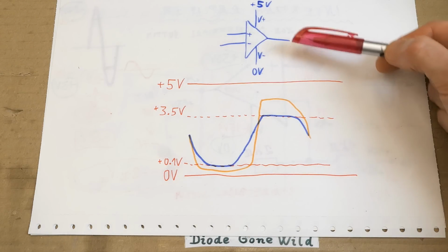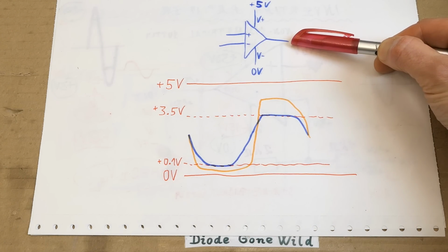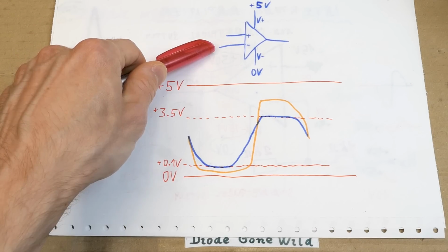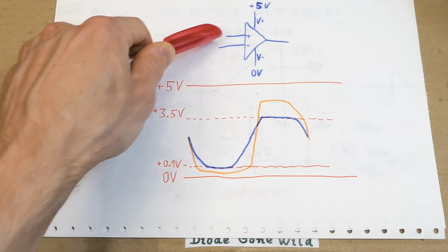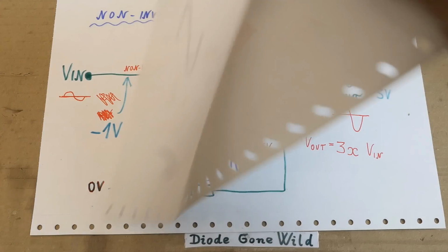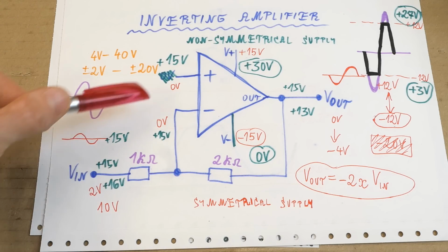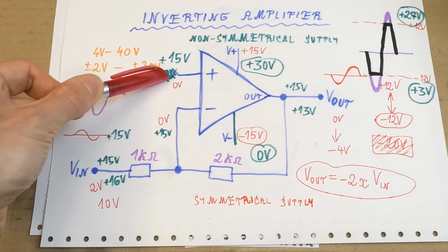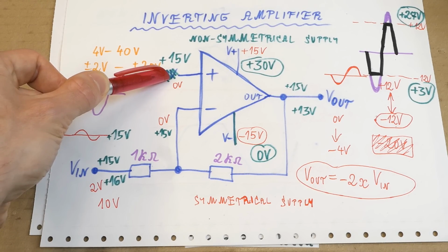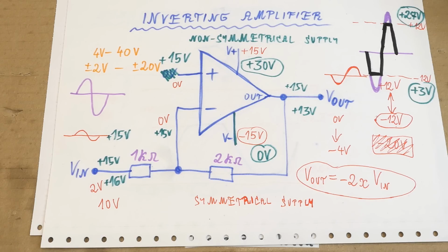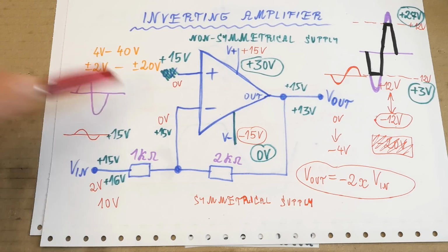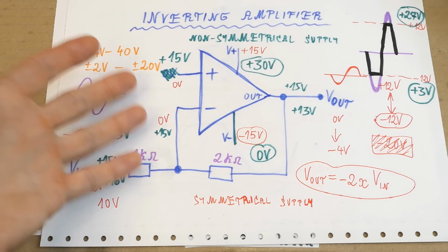And not only is the output voltage swing limited in op-amps, but also the range of input voltages. There is always some range of voltages you can have at the inputs. And op-amps, unlike comparators, are typically running with a feedback and not in a saturation. So the feedback basically keeps the voltages at the inputs the same. And that's why in op-amps, the datasheets typically talk about the common mode input voltage range. The voltage of both inputs basically travels together, and it can travel in a certain range. And this is where a lot of beginners go wrong.